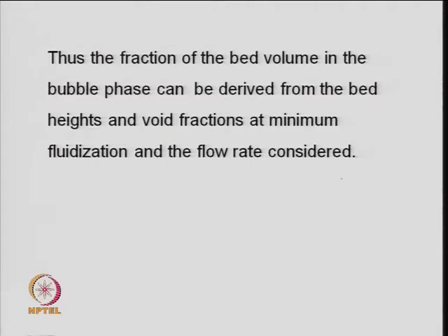The fraction of the bed volume in the bubble phase can be derived from the bed heights and the void fraction at minimum fluidization and flow rate. Basically it is a mass balance. You know the fraction of solids in the bubble phase, the fraction of solids in the emulsion phase, and if there is some other wake phase, all these together give the total fraction of the void fraction of the bed. One can calculate the total fraction of solid in the bed simply. Same thing for the height of the bed: the minimum fluidized bed height is related to the void fraction of the bed. It is just a mass balance for the solid, so one can calculate that.